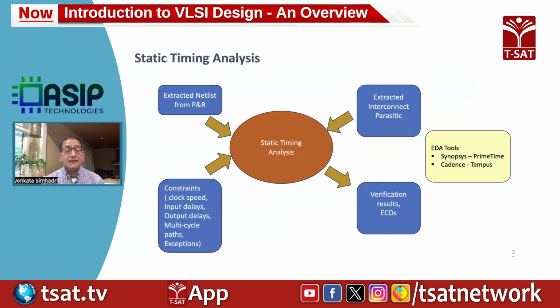Then you also define, there may be some sequential paths in the design that may be multi-cycle or false paths. There may be some exceptions. So you put them all into a constraint file and you feed that into the tool. And then you run the tool to analyze the results. So the tool will give you an output. To begin with, it says, okay, the design is meeting timing or not meeting timing, or if the design has some violations where it's failing the setup time and hold time requirements.